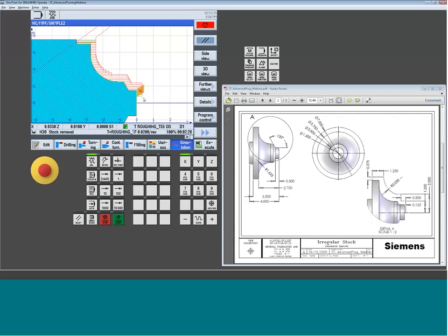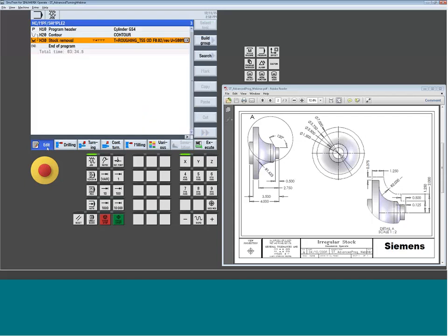It machines through the part. So here, this is a perfect example of where potentially I'm getting some dead passes because I had to tell it I had 250 material in my Z, but maybe I didn't have it on the face of the part. So if I want to change this around a little bit and add some kind of stock, I do have to draw that stock. So what we're going to do is just add a drawing. We're going to quickly draw this irregular stock shape. And I'm just going to use this little detail to give me some rough dimensions to draw the stock.